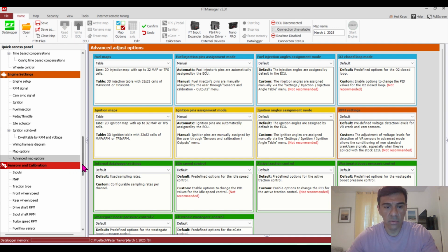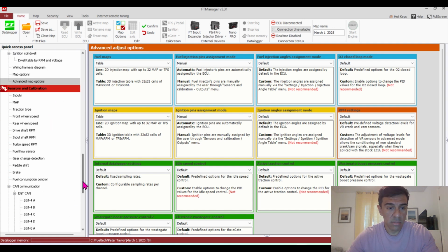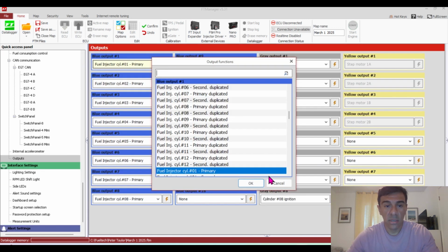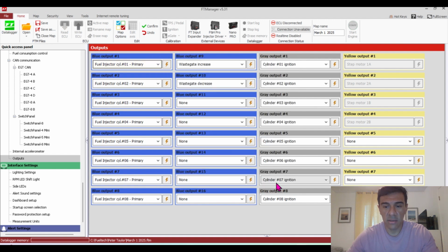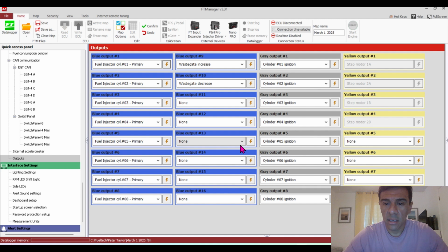And that'll allow you to go down that side. That will allow you to change these around, right? So let's say you're using a Ford harness, I'm sorry, a Chevrolet harness on a Ford vehicle. I've helped a guy, I was like, hey, just wire this thing up like if it was a Chevrolet, plug the injectors as if it was a Chevrolet firing location, and we move the outputs here, and then you can test them. This is to test that particular output, you know, to make sure that it matches the cylinder where you have it at. And so that's the cool thing about the FuelTech as well, is you can test the outputs.